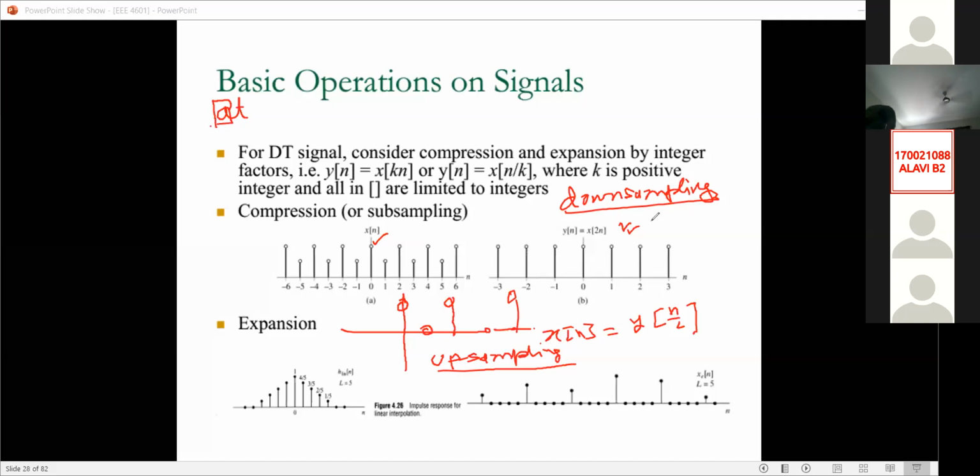So your upsampling and downsampling: downsampling eliminates your samples by a factor depending on how many times you need to downsample. Upsampling is the reverse operation of downsampling, but the thing is that your signal cannot be exactly recovered. For this reason, we need some statistical and mathematical technique to estimate the samples where the values are 0, okay? In your numerical method, you know, there is a mathematical technique we call interpolation.